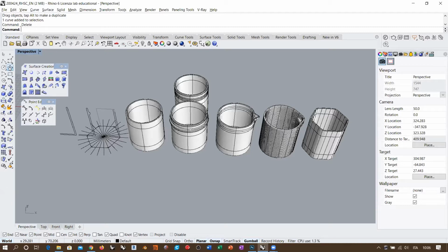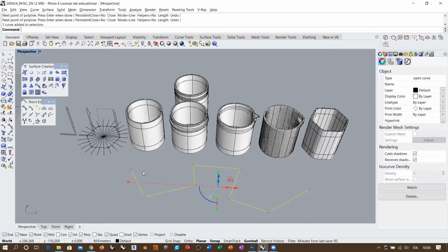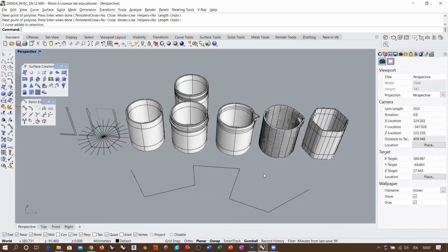In general, if you think about it, the polyline is another particular case in this sense, in which you have a degree 1 curve, and you have a set of knots, which are in this case coincident with the control points. Why? Because we saw that in a degree 3 curve, the uniform knot vector contains only a sequence of values that never repeat along the vector, okay? With the exception of the first knot and the last knot, which have full multiplicity, okay?